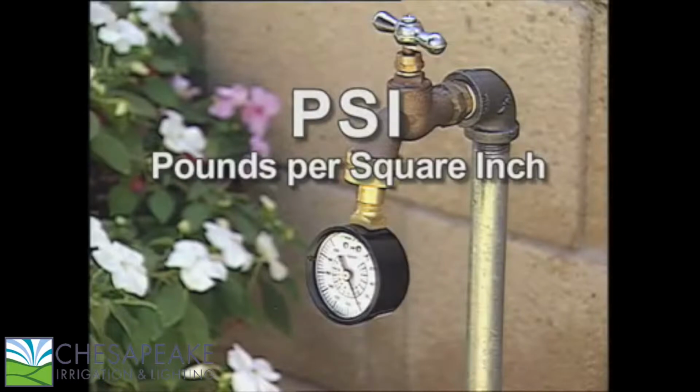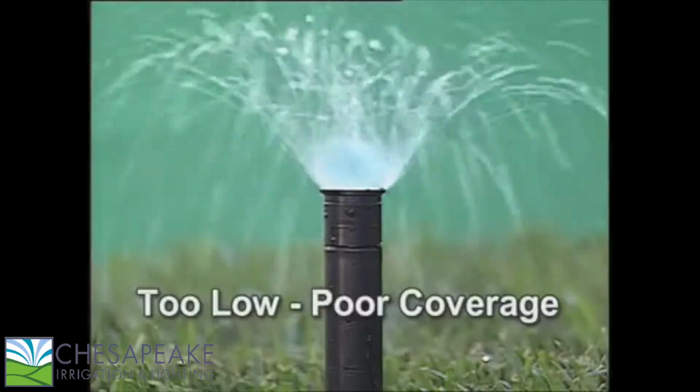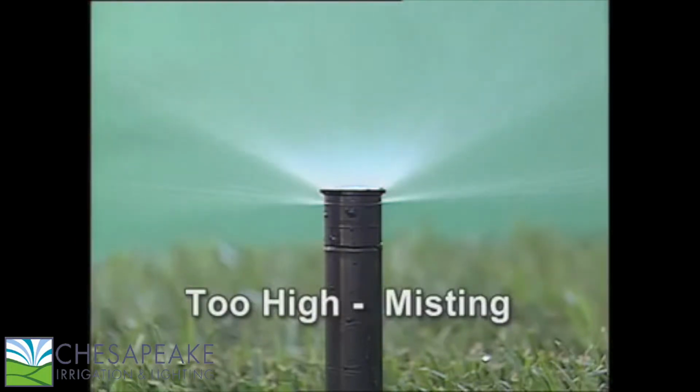Knowing your property's available water pressure will be a factor when calculating how many sprinkler heads can be operating at the same time and still be effective. If the PSI for your yard is low, fewer sprinklers may efficiently operate at the same time. If the PSI is too high, that also will have an adverse effect on the sprinkler's performance.